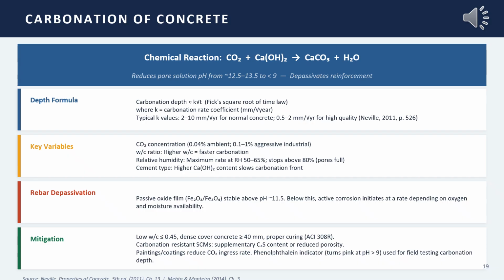So, from a design standpoint, the main defenses against carbonation of concrete are basically the lower water cement ratio, good concrete cover, and proper curing. Remember that carbonation depth can be measured in the field using phenolphthalein indicator, a pH indicator solution that turns pink above pH 9.